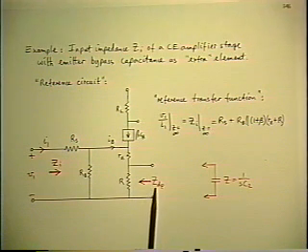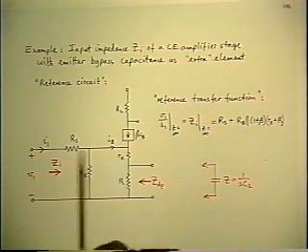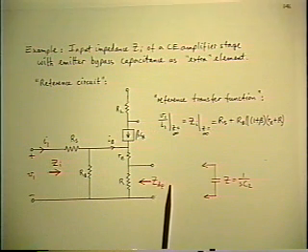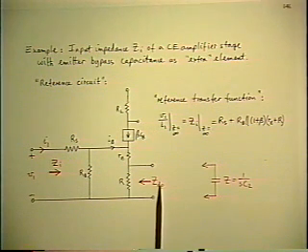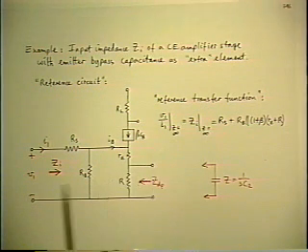And the first driving point impedance is ZD, or RD in this case, because everything is resistive. And it's a single injection calculation in which the original input of the transfer function is 0. So this is when you have to be careful as to what the input is.